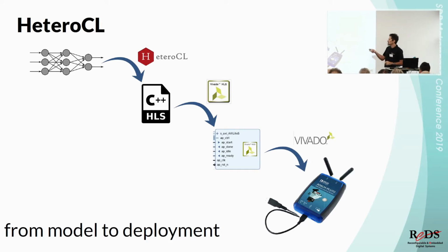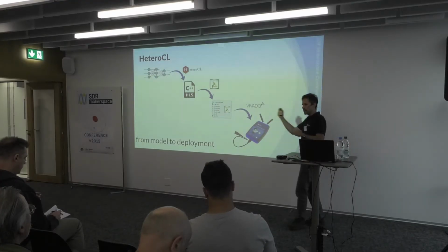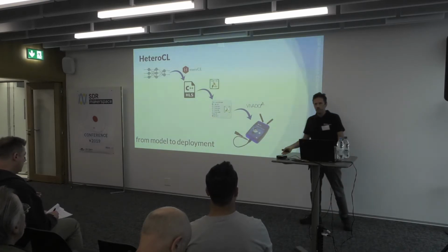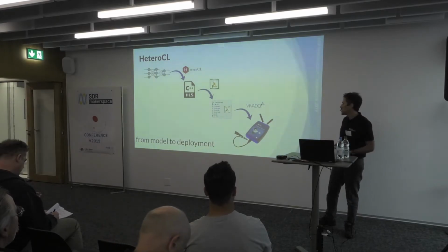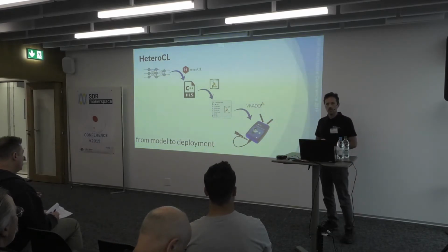And many vendors, this is Vivado HLS, but the tool chain supports also different high-level synthesis tools, provides you with a nice small, potentially AXI-interfaceable IP that you can deploy on your system. So you can probably integrate that also in the framework we have seen before. Okay, so there's another step there, and then what you get is not, as in the previous technology, directly utilizable for you. You still need to integrate this system with your design or with whatever you have on your final platform.